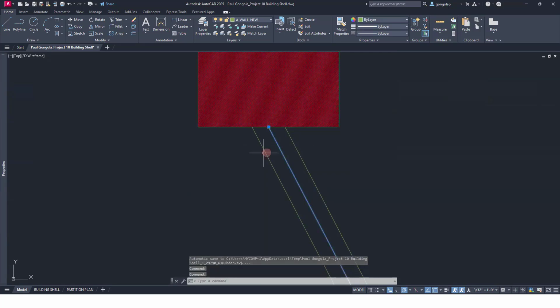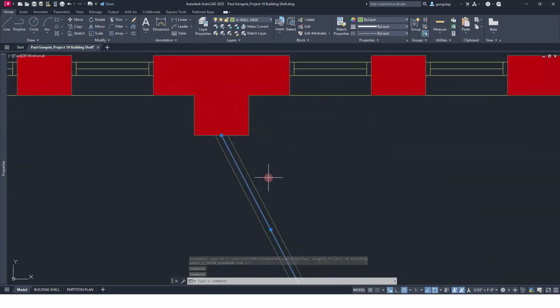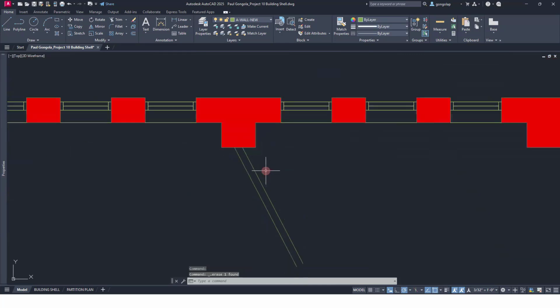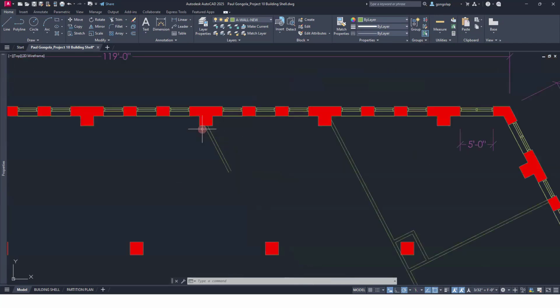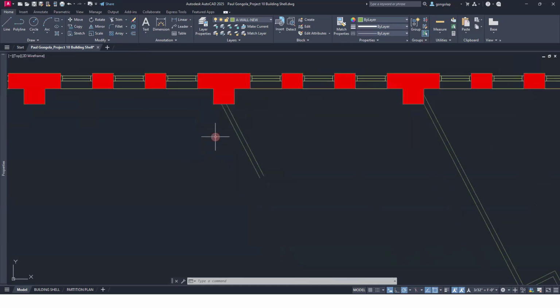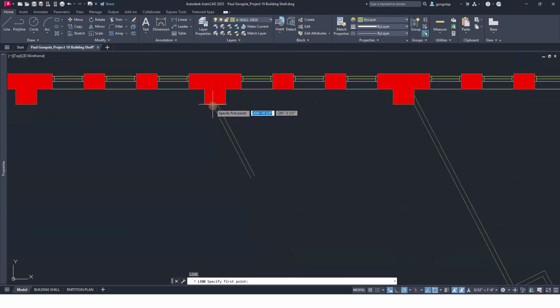And I don't need that center line anymore. That was just for me to get the 5 inch partition correct. I used the center line to do the offsetting, half of 5 inches up to the right and half of 5 inches down. Okay, now let's O-track 16 feet one. So with my line tool, I'll just... Sorry, Paul, what angle was that at? This is at 297 degrees. Okay, thanks.